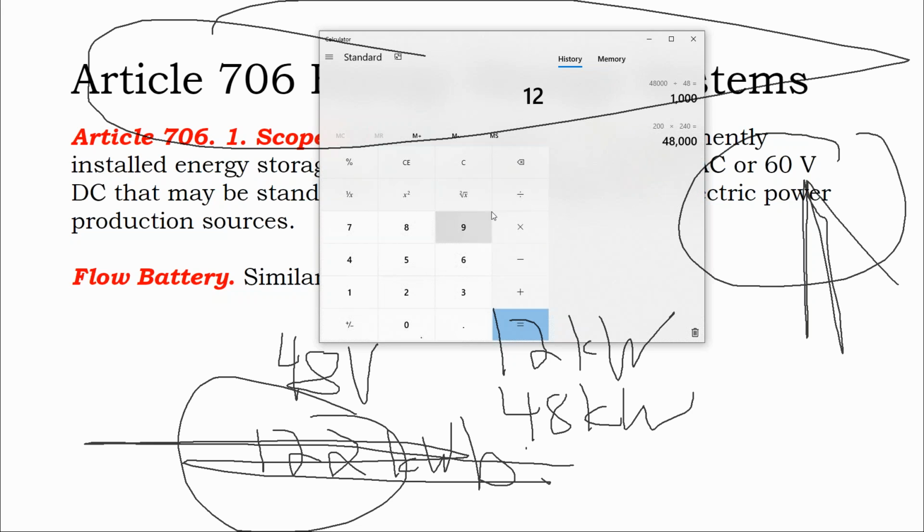What's more typical is a home with maybe 12 kilowatts as a backup solar inverter, but even then you're using 250, 300 amp cable and getting up into 4/0, which is like the thickest welder cable you've seen. And beyond 4/0, that gets you into utility scale cable.